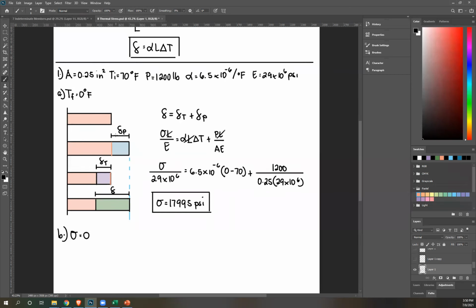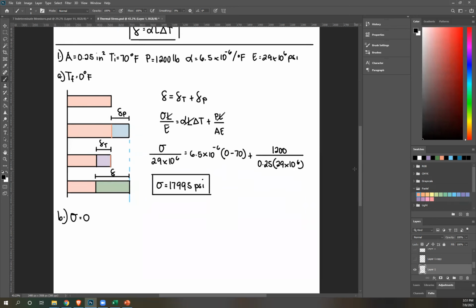the reason why this is experiencing stress is because you stretched it out and then it made it deform. And then you're stretching it out again. Okay? So to make it not experience stress, we need to create a situation where you don't need another applied force. So that means we need to create a temperature wherein its expansion will lead it to the same point as the original applied force. Okay, so in drawing,